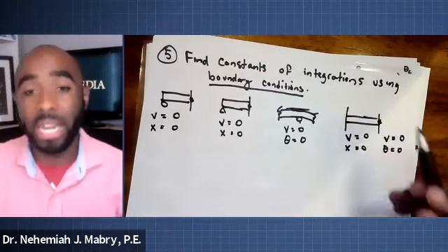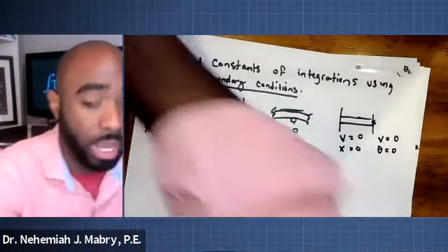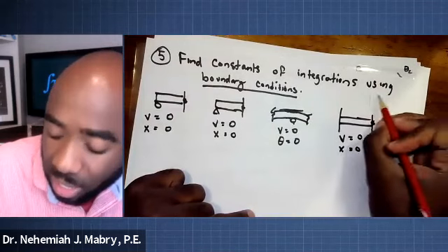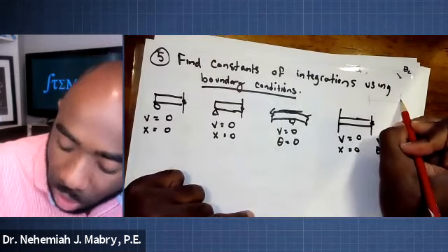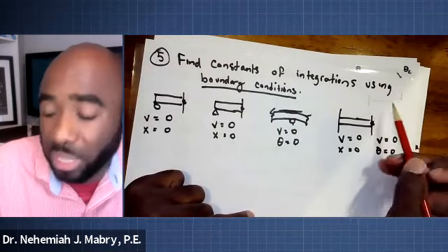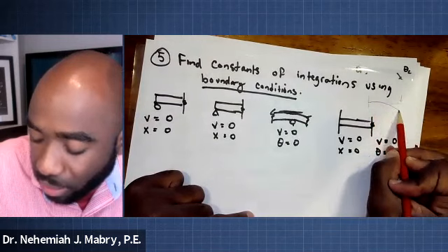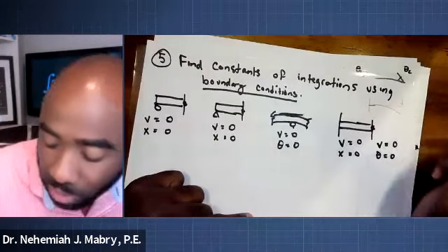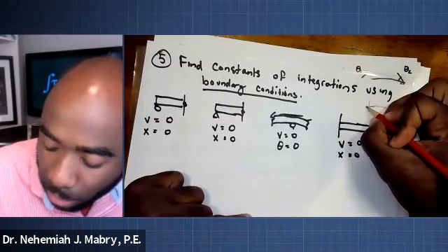Because at this very end, when it's a fixed end, you're going to have it come out a little ways. Let me see if I can draw that with a pencil. I don't want to mess up the notes. But let's say you have a fixed end. See that? And over here at the end of the beam, you have a load. Well, the deflected shape is going to actually come out a little bit and then begin to deflect. So at the very end of it, you're not going to have a deflection, nor are you going to actually have an angle happen. It's going to be flat.